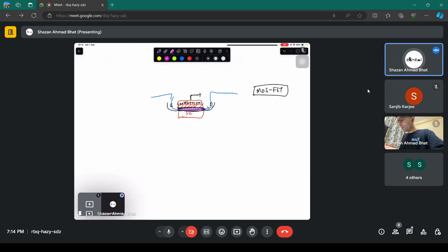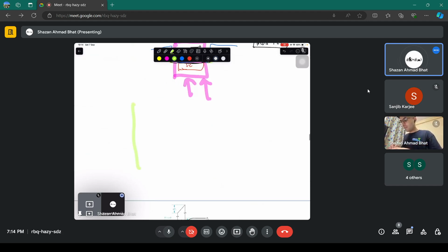That's why if you understand MOS, this particular thing, it is the building block of every field effect transistor, every transistor which is being used. That's why right now we don't directly jump into source and drain contacts, because they are just contacts used to extract the currents. The main thing is to induce the electrons just below the oxide. You have the metal, oxide, and then there is semiconductor. This is metal oxide semiconductor.